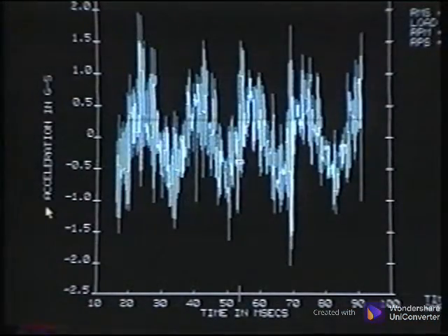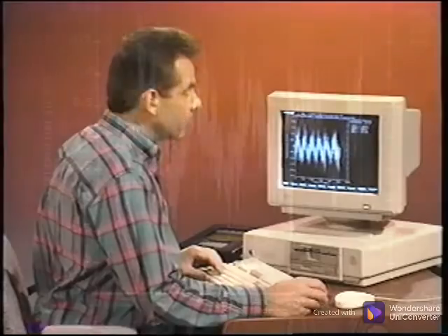When we display an acceleration time waveform from the same fan point, we see an underlying sinusoidal pattern. However, notice how significant the high-frequency information is displayed. Now we can see a tremendous amount of high-frequency data. The imbalance of this shaft is so significant that it is beginning to damage the fan bearings.